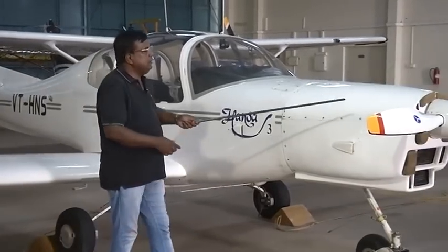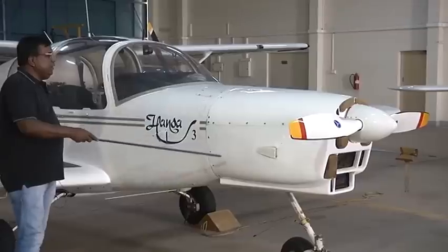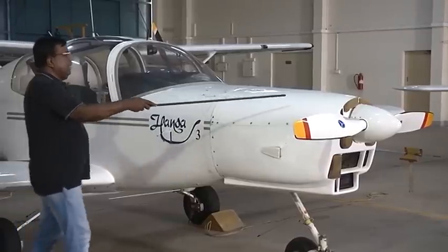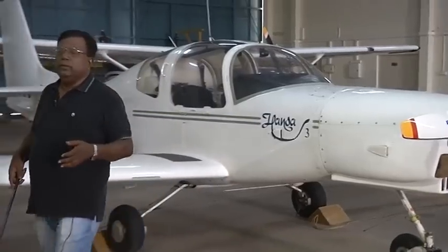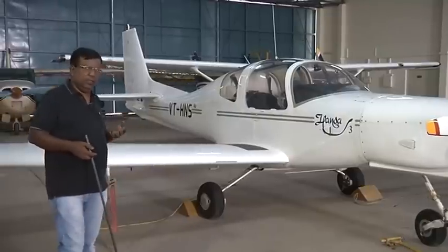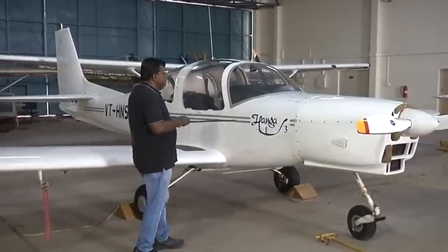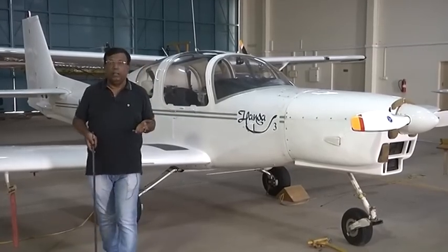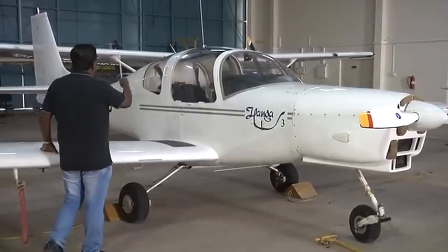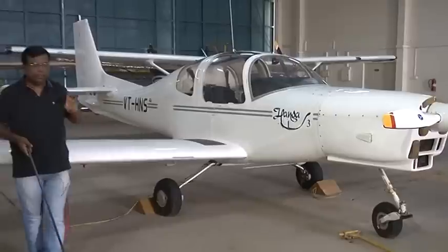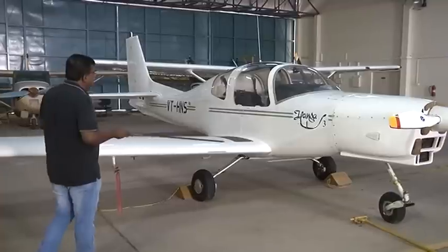Second thing you see here, this is the thrust line, okay? And if the vertical CG is very far away from the thrust line, then this thrust will be giving a moment about the CG, and the pilot will have to make some corrections before he goes for a flight. So the natural tendency would be to try to keep the CG on the central line. But it may not be possible all the time, because sometimes the wing is a low wing like here, sometimes the wing could be a high wing. So you try to ensure that the CG in the vertical height is close to the central line.